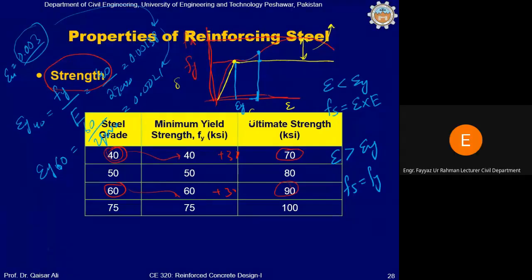You see, this actual stress strain curve, we have idealized as a bilinear curve. You can see this yellow color curve. In that, if you look below this value, if strain is below EY, then the stresses can be calculated because there is a linear relation. You can see here it is in the elastic limit.